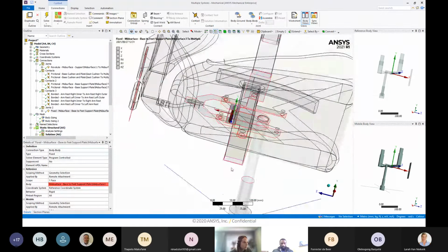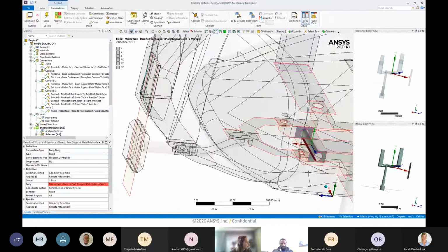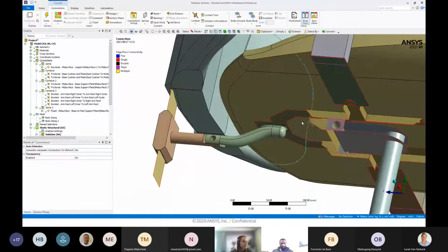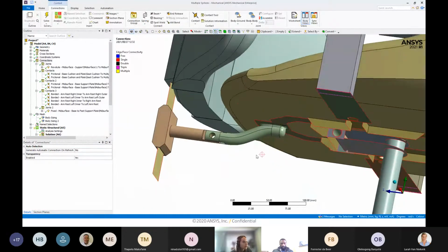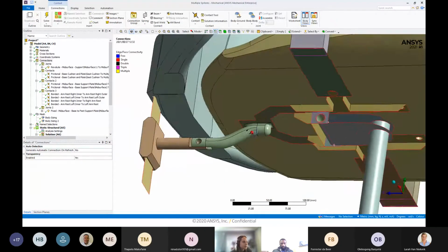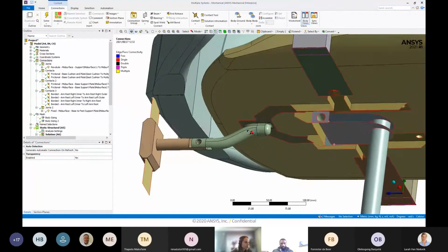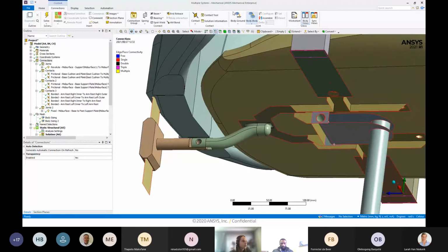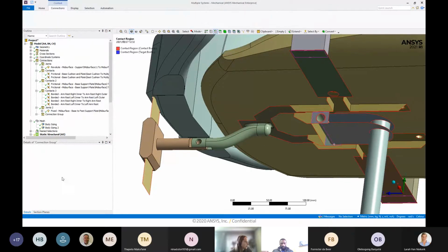Then for this, I'm not entirely sure what's happening here, but in this case, I'm also just going to bond this surface to this rod. If you want to capture more detail, you could always do a submodel in an area like this, but this is something we'll cover next week. Okay, so let me just add another bonded contact here.